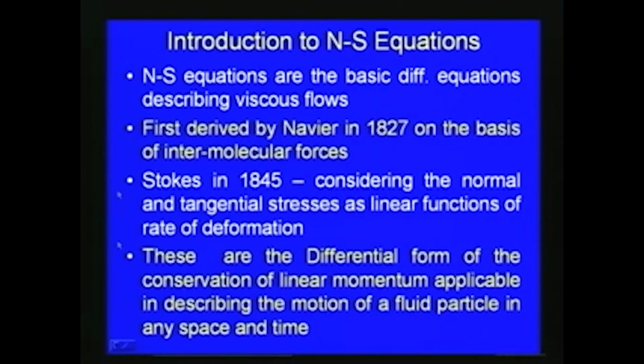We have already seen the form of Cauchy's equation, and based upon it, the Navier-Stokes equations were derived in 1827 by Navier on the basis of intermolecular forces, and in 1845 by Stokes by considering the normal and tangential stresses as linear functions of the rate of deformations. These are the differential form of the consideration of linear momentum, applicable in describing the motion of a fluid particle in any space and time.